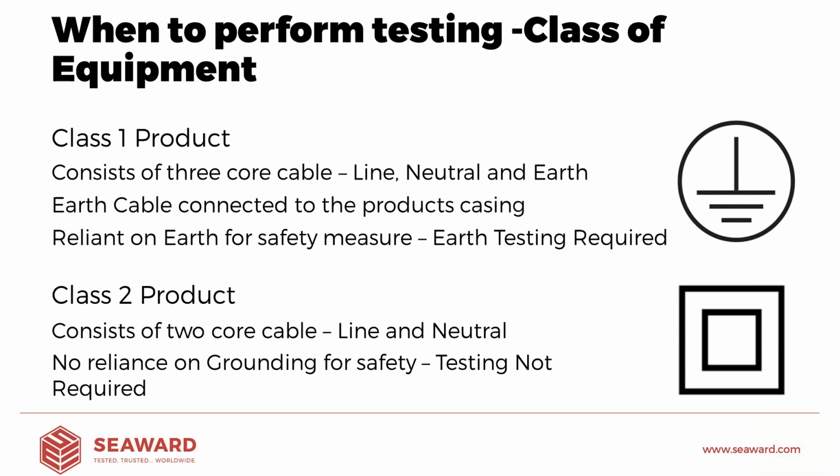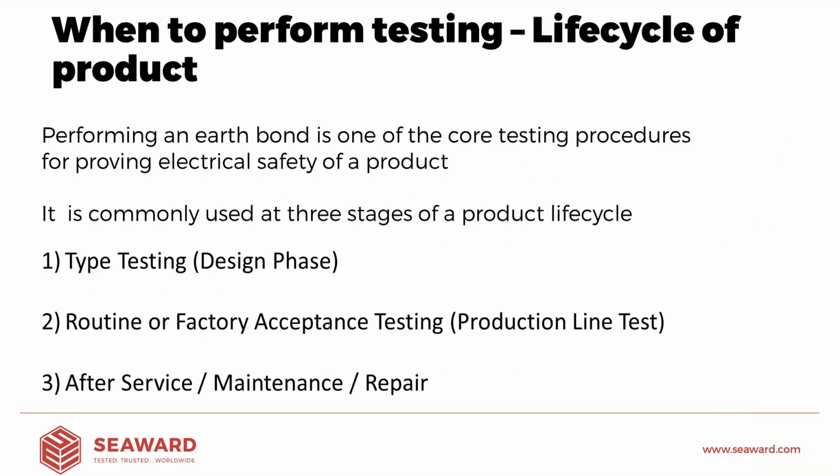safety. So for a class 2 product, it's typical we don't need to perform an earth test, generally because there just simply isn't an earth connection that needs testing. So always on a class 1 product, we should be performing earth testing.